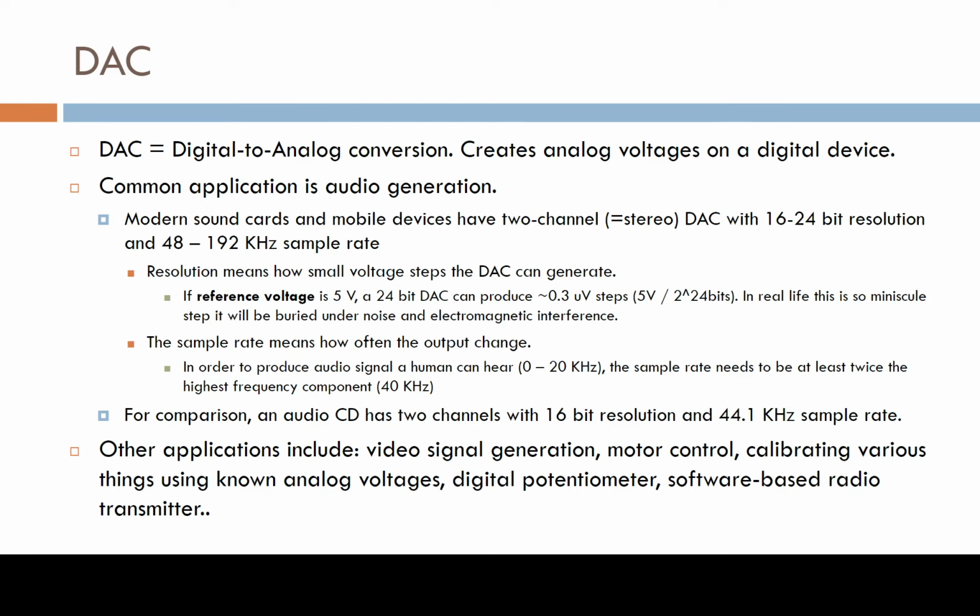So basically the data is in a table and there's a timer that goes once in a sampling time, reads that data and sends it to the DAC. So it's not a continuous signal, but a discrete time signal.